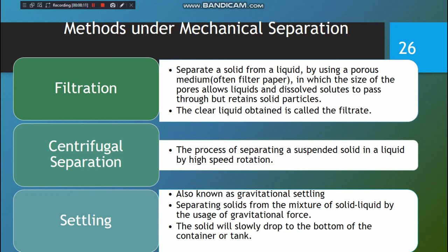To summarize the concept of settling, based on the statements that I've mentioned before, settling, also known as gravitational settling, is a method of separating solid from a mixture of solid and liquid by the usage of gravitational force. Here, the solid, which has higher density, obviously slowly drops to the bottom of the container or tank, which is then sucked by a pump to separate the solid using a filter.